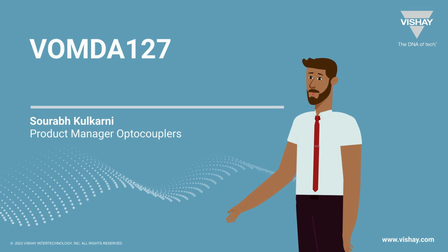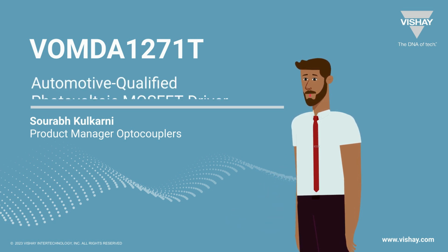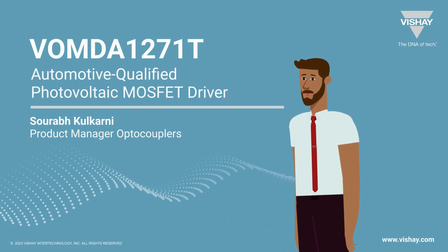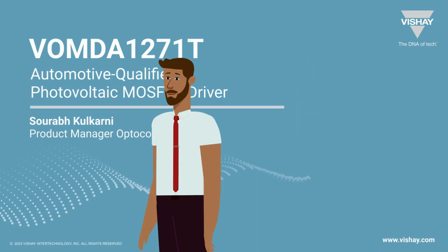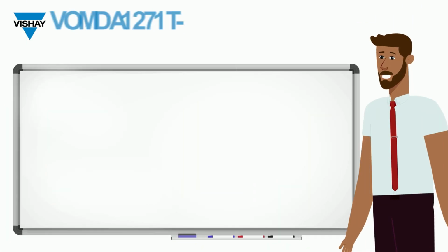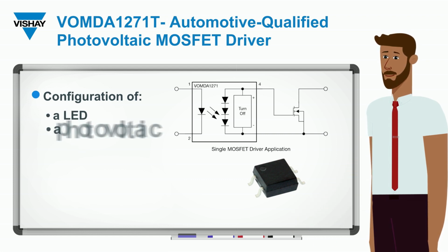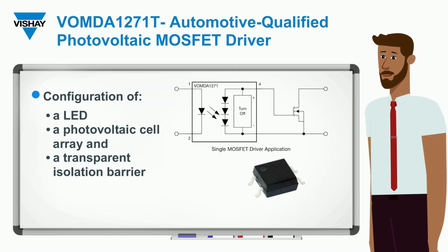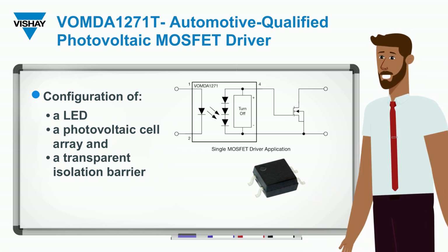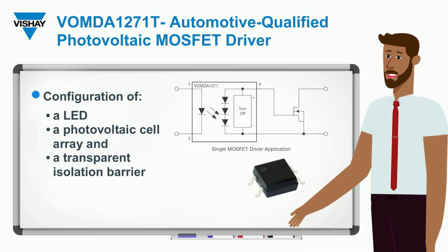Today I will be talking about Vishay's Automotive Qualified Photovoltaic MOSFET driver VOMDA1271. A photovoltaic MOSFET driver is essentially a configuration of a LED and a detector chip consisting of multiple photovoltaic cells. The LED and the detector are isolated using a transparent isolation barrier.